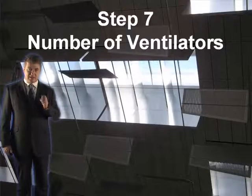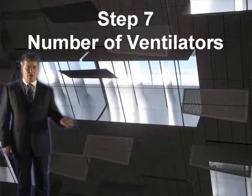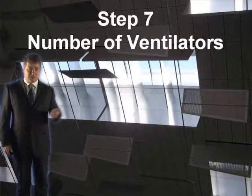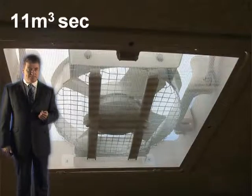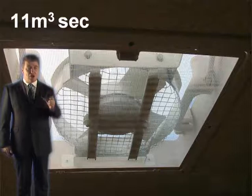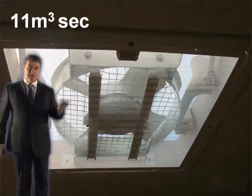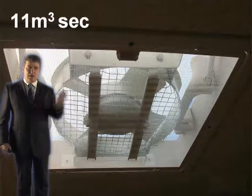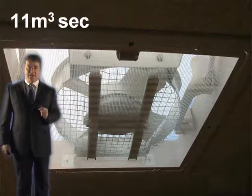Now we're going to look at step 7, which is determine the number of ventilators in the reservoir. We know that the proposed fans, as we said, have a capacity of 11 metres cubed a second. And in this situation, you do not have to assume a fan was lost. Sometimes you have to take out a fan if there's a reason to believe a fan could be taken out. In other words, if the stores are right next to the fan, it could take it out in a fire. Well, in this case, the atrium's sterile, so it's very unlikely a fan will be taken out. So you can progress on the assumption that no fans are taken out.